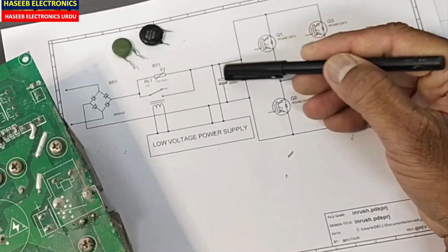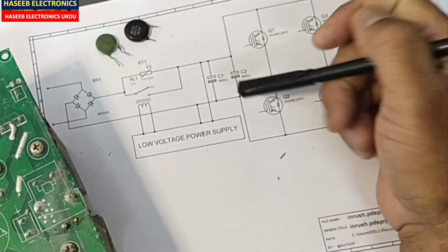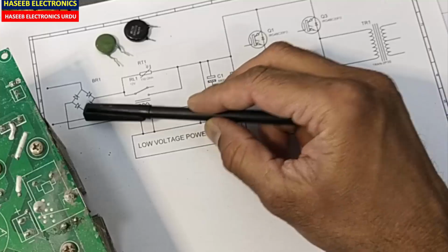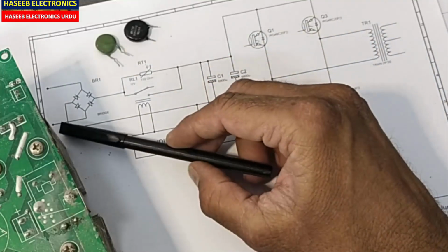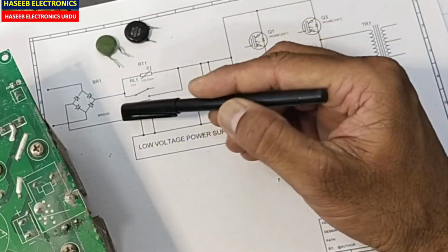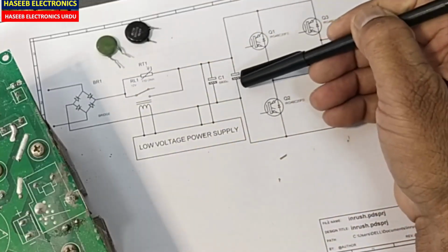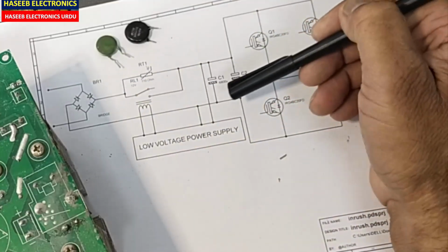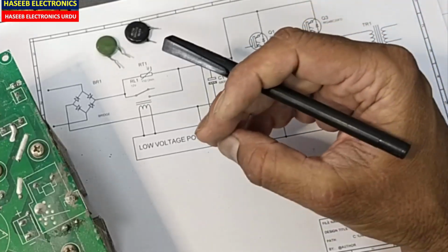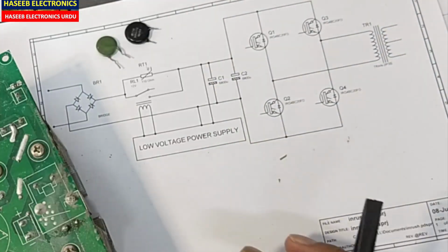These capacitors draw a huge current surge when the power is applied. It can damage the bridge rectifier, it can trip the circuit breaker, anything. Or if we have a huge size fuse, it will be damaged. To protect from any damage and to protect these capacitors, because when the capacitor is empty, its internal resistance is equal to 0. That is not exactly 0, but suppose it is equal to 0.